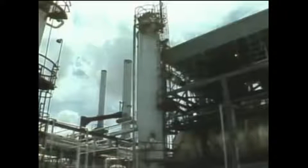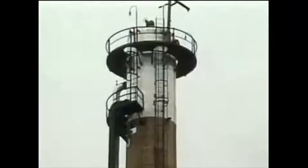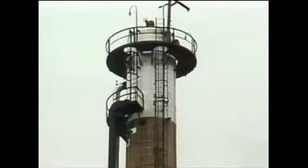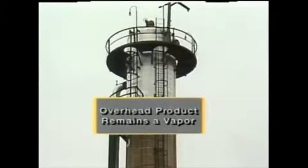Another type of tower is called a stripper tower because it strips lighter components out of the products. However, unlike most other distillation systems, a typical stripper tower system does not condense the overhead product into a liquid. Instead, the overhead product remains as a vapor and is sent for further processing. Some towers are named according to the chemical product that is being separated. For example, a tower that separates propane and lighter components from a feed can be called a depropanizer. The overhead product from a depropanizer contains mostly propane and some lighter components. Components that are heavier than propane end up in the bottoms product.